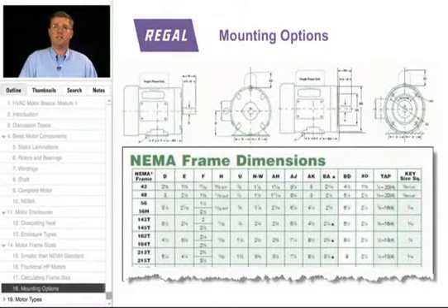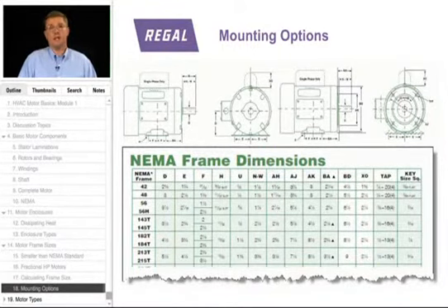The third digit in the NEMA T frame motors tells us the distance between the mounting footholes in the bottom of the base. So it is possible to switch frame sizes if you understand where the center of shaft is, and on the T frame motors, a 143T or a 145T frame may be used if the motor is punched for the holes in the bottom of the base.